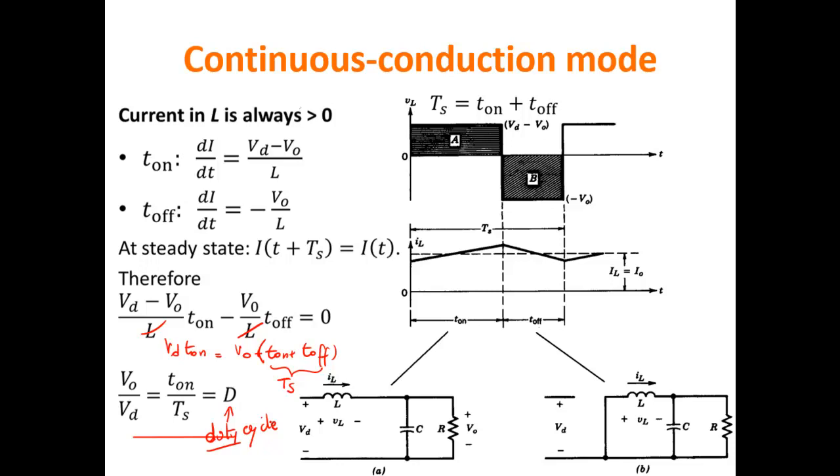Okay. Again, we have this interesting possibility that we can keep the switching time fixed, and then by adjusting T on, we can adjust Vo if there is a change of Vd, or if you want different Vos, as for example when you are providing a power supply for a CPU, which needs a different power supply depending on the, let's say, computational load. So I mean, the operation of the DC-DC converter in this case is relatively simple.